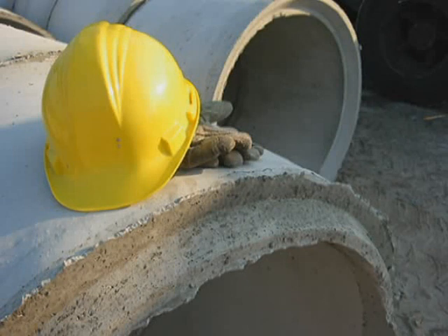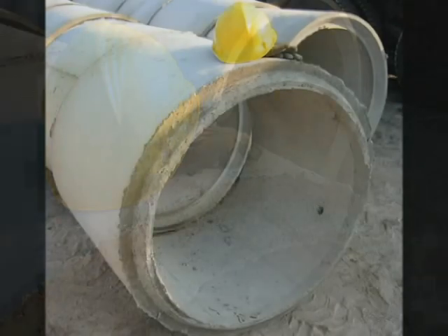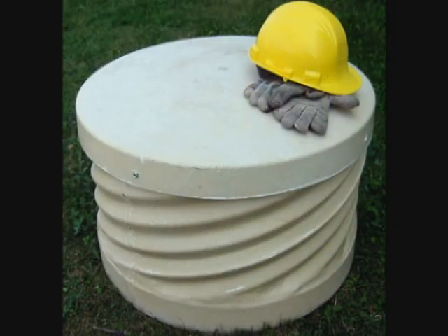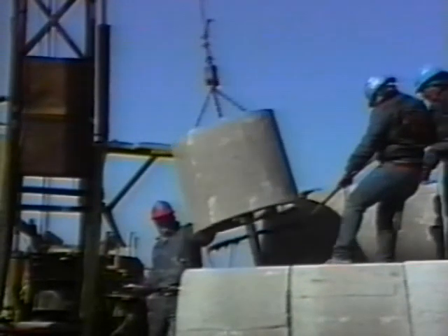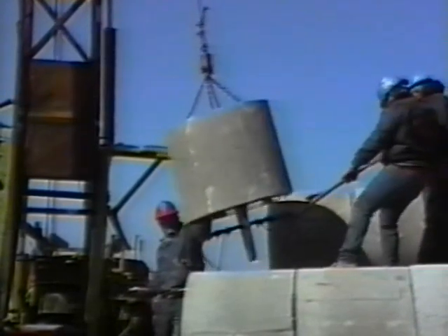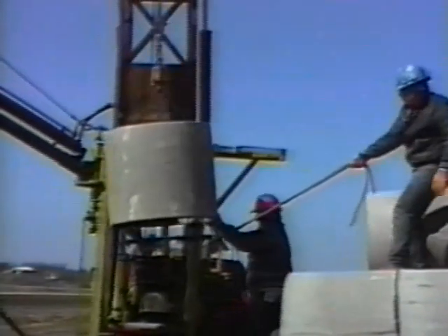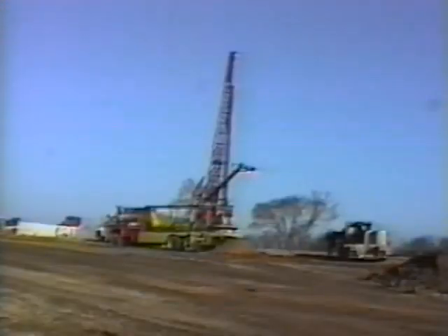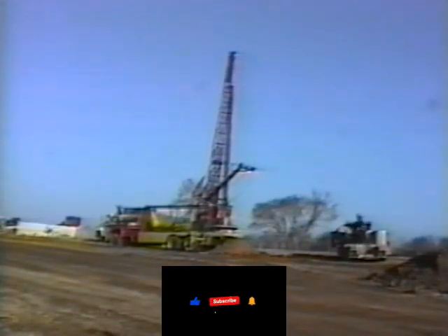The next step in this process is the installation of the permanent casing, which can be manufactured from concrete, galvanized steel, or fiberglass. Shown here is the installation of concrete casing using a tile setter. The annular space between the casing and the borehole wall at the aquifer area is filled with permeable material, such as gravel or washed stone. The well is grouted and developed to a sand-free state, as per Regulation 903.